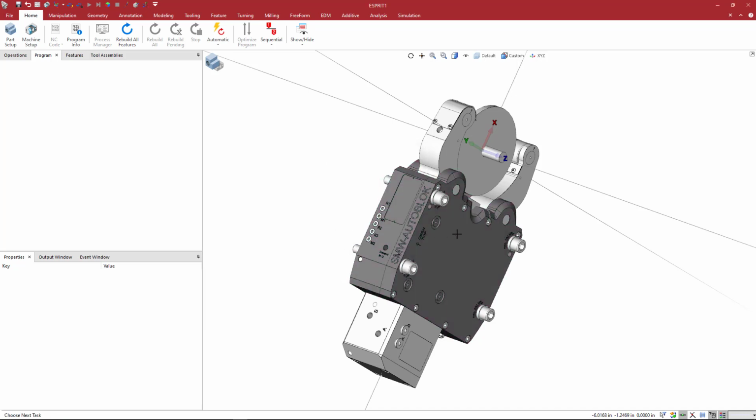Another thing that you can do is inside of the selection filters here. If you're not able to select a solid model, you probably have your solid bodies unhighlighted. So here you can see all the bodies. You want to make sure that you can pick the solid model by having, if you just click outside of this box here a couple times, you can highlight everything. But this second icon down here is going to be your filter.